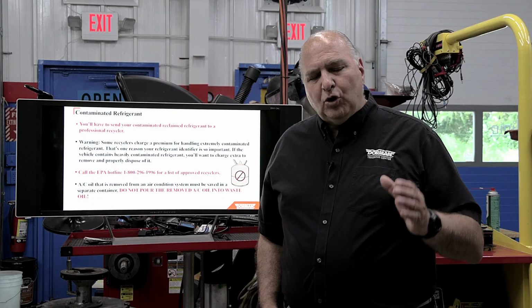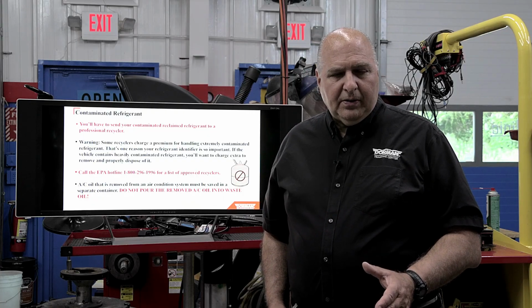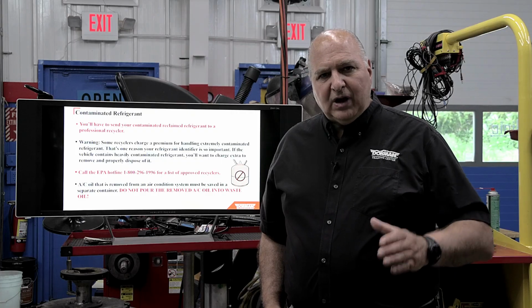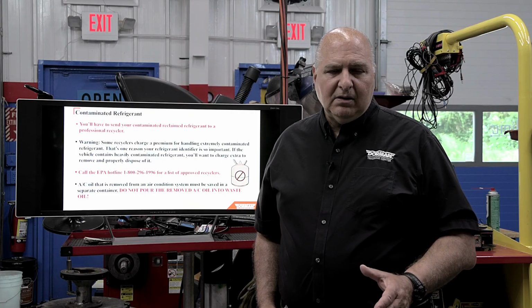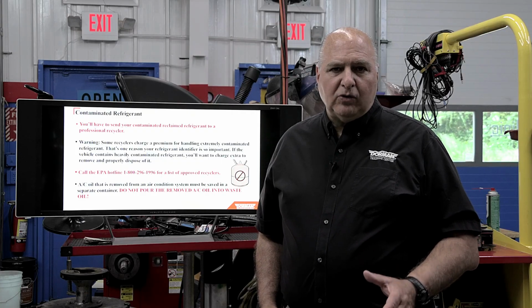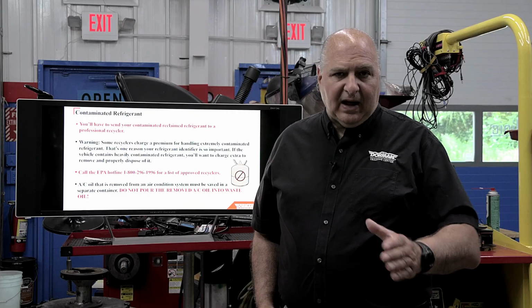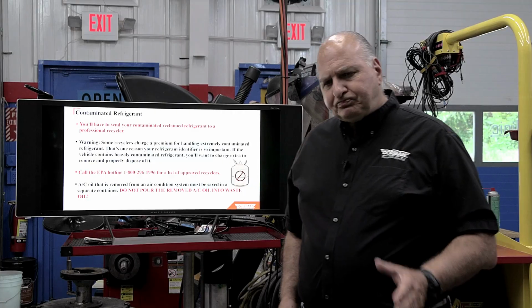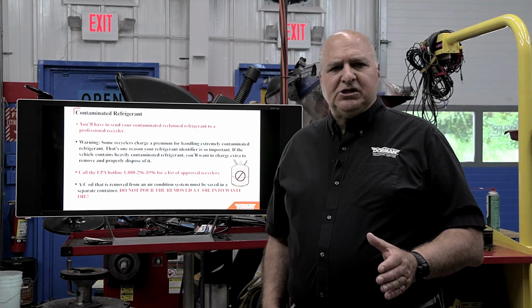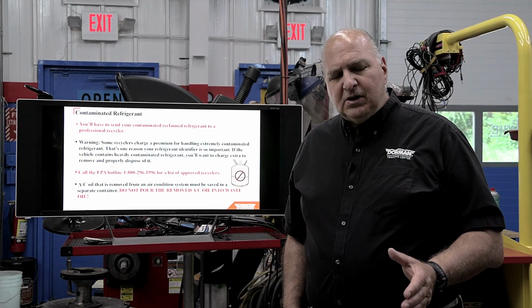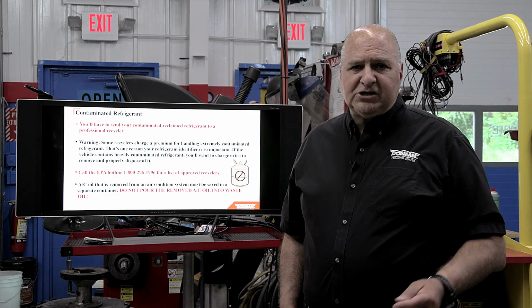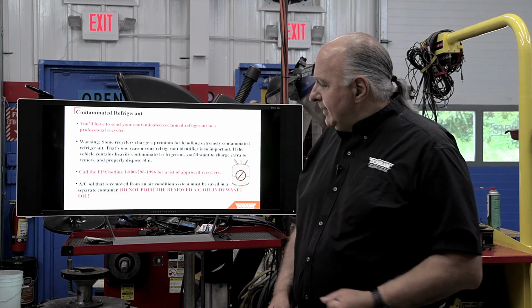Think about in the winter, the job of the AC system is to remove moisture out of that cabin, okay? And it will clear your windows way quicker than not having AC work. So sometimes it's a good idea to say to your customer, let's check your AC system, do a performance test. Maybe you're low, and if you catch something leaking early, it may save them money in the long run, okay?